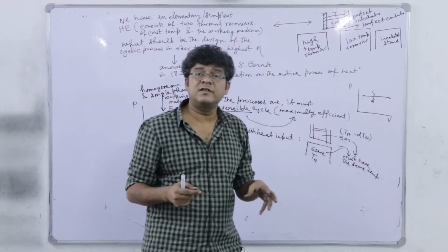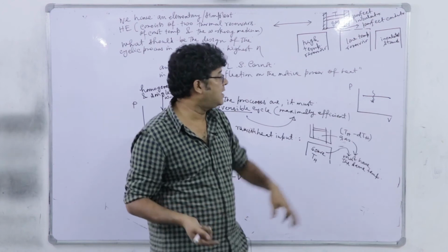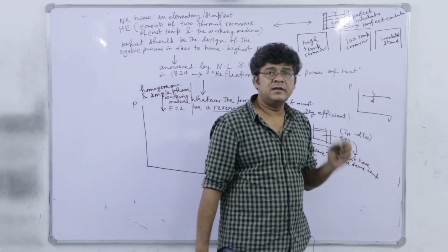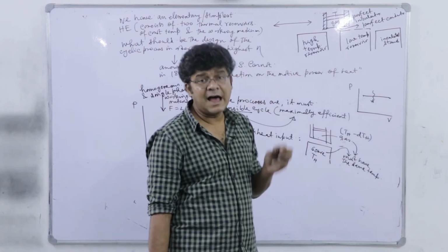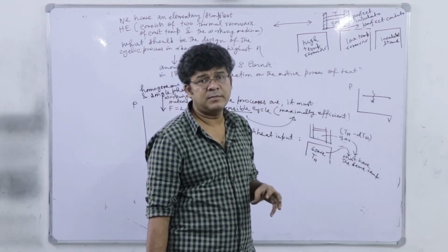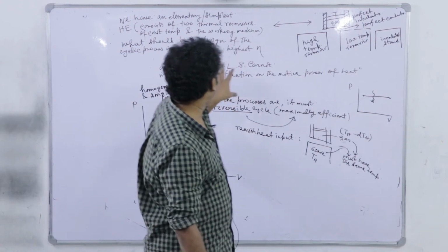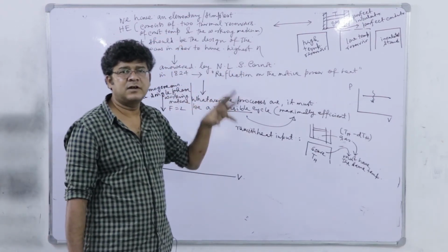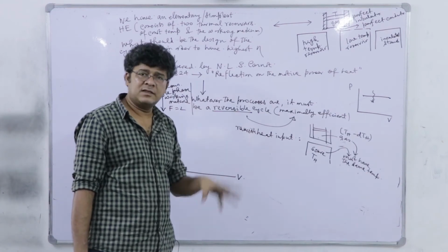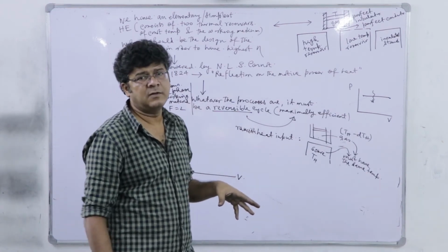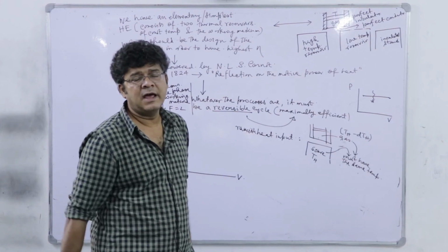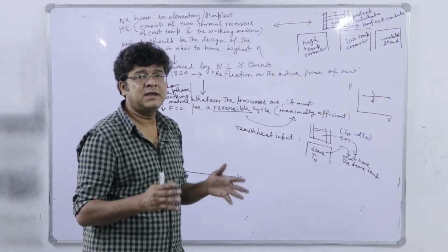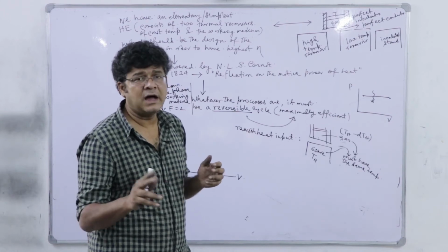Then, at least theoretically, we can implement this reversible isobaric heat input step. However, here in this elementary structure we have a constant temperature thermal reservoir, and with that, if I have to implement a reversible heat input step, then it must be isothermal. There is no other option.